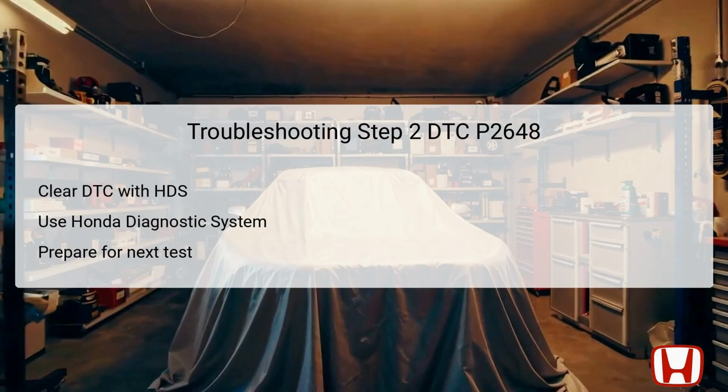After initiating the diagnostic process, the next step is to clear the diagnostic trouble code, DTC, using the Honda Diagnostic System, HDS. The HDS is a specialized tool designed for Honda vehicles, enabling technicians to reset codes and perform advanced diagnostics.